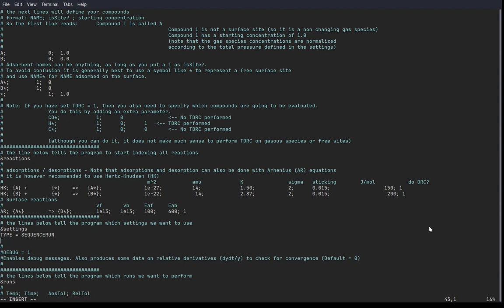One that's really useful is this one called use timestamp. Make it 0. When it writes the results into an output folder as you run the simulation, it will try to make the folder name a timestamp, and that's tough because if you want to get back into a lot of simulations, all the folders are going to have different names. If you make it 0, it'll just call the folder run, which is nicer.